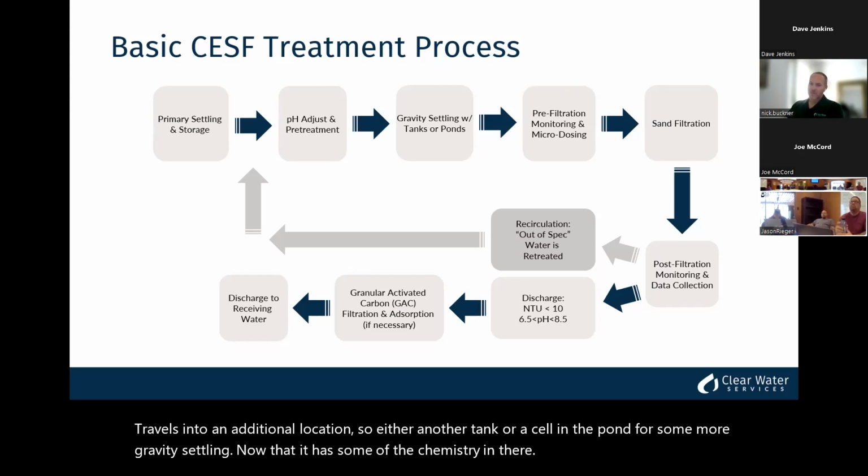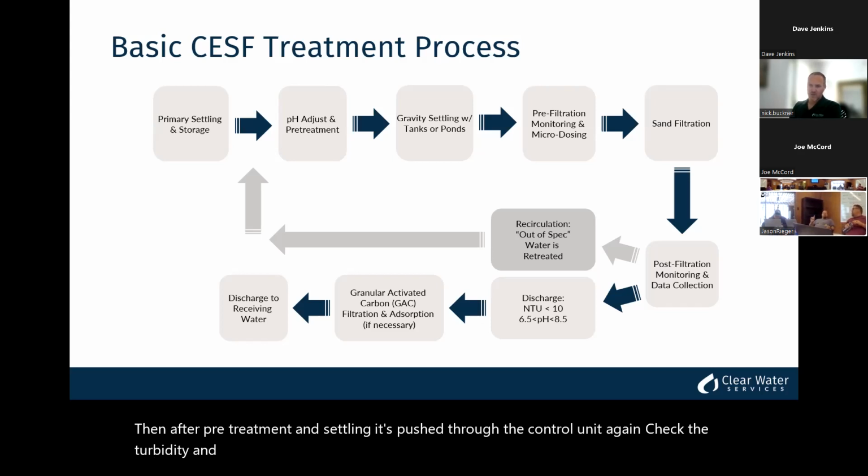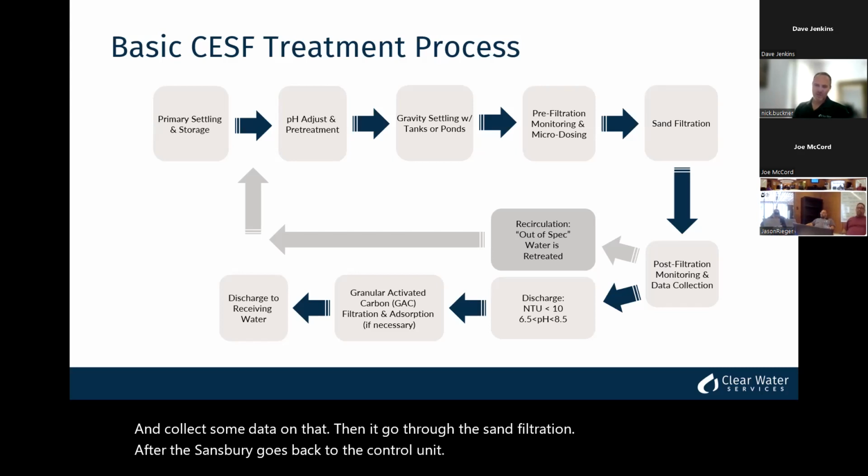Then after the pretreatment and settling, it's pushed through the control unit again to check the turbidity and pH and collect some data on that. Then it goes through the sand filtration. After the sand filter, it goes back to the control unit for final monitoring.